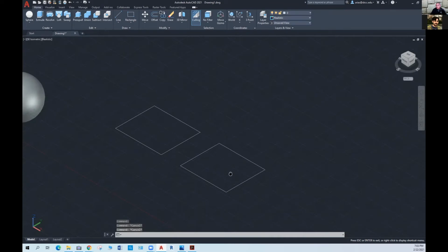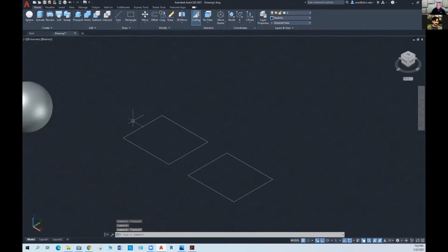And so if I apply a tool like this, then I can use these tools, they're 1, 2, 3, and 4 tools, to create geometry in AutoCAD out of a profile, right? And so that's the idea. I can create solids with the primitives, or I can use 2D profiles and then use these tools to create three-dimensional objects based on those profiles. Or 2D objects in lines.